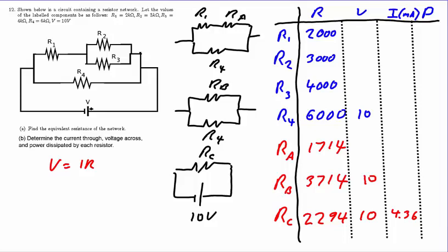We now have two lines with 2 out of 3 quantities calculated, so we can simply finish the calculation using Ohm's law to yield 2.69 milliamps for RB and 1.67 milliamps for R4. At this point, because we want to get 100% credit on the problem, we choose to invoke our checksum. Indeed, since the voltages were equal on the two components, the currents must sum to the total, and if we take the 1.67 and add the 2.69, we do get 4.36, meaning we can trust our calculations so far.